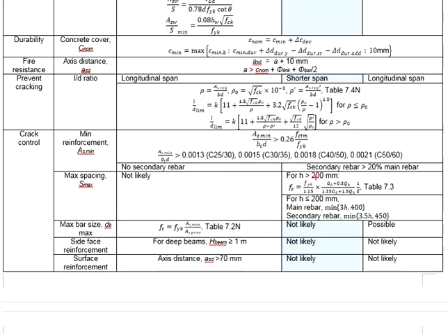The most common one would be the minimum reinforcement areas, which is known as the AS-min. AS-min quantify the minimum bar area required as a percentage out of the effective cross-sectional areas of the concrete member.